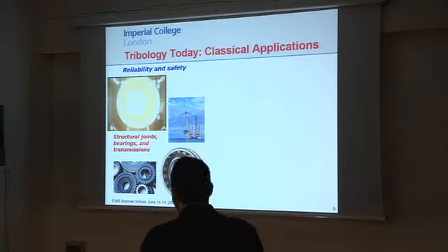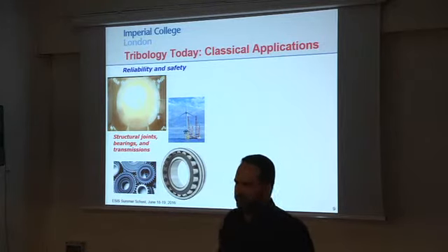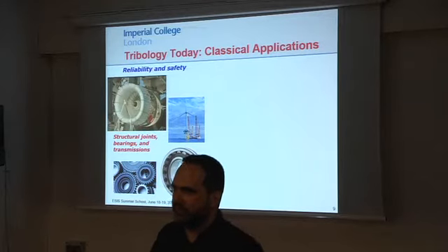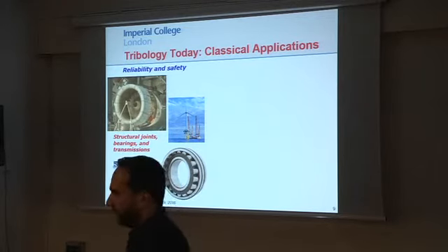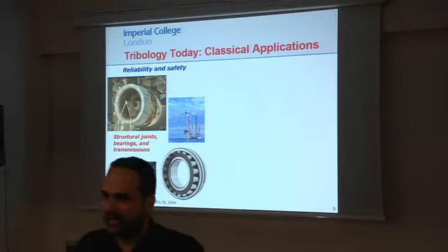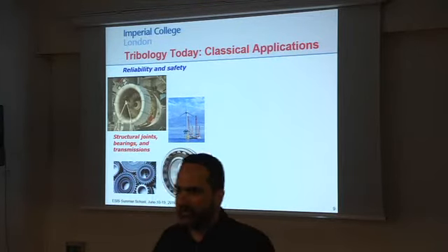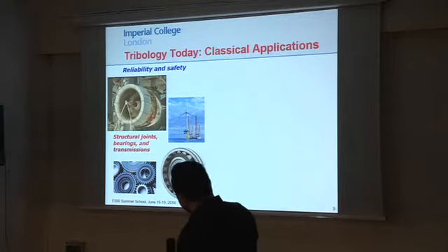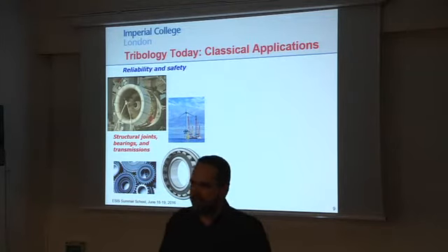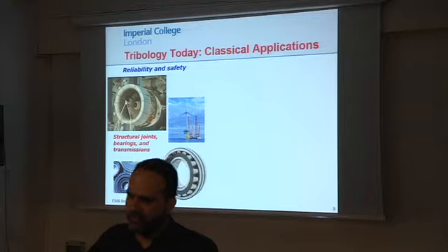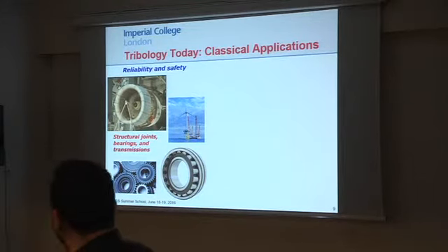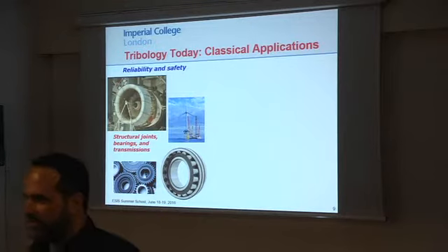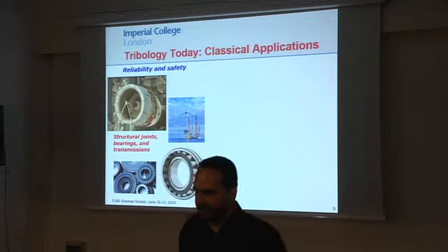But if it is released during the flight or during takeoff and landing, which are the most dangerous parts of the flight, you want that blade to be contained within the casing. And that's where our impact engineers do a great job, because in that case, they show that yes, if the blade is released, it is encased within the engine, it doesn't fly through and kill people in the fuselage, and therefore this thing can be certified to fly, because even if it fails, it fails safely.